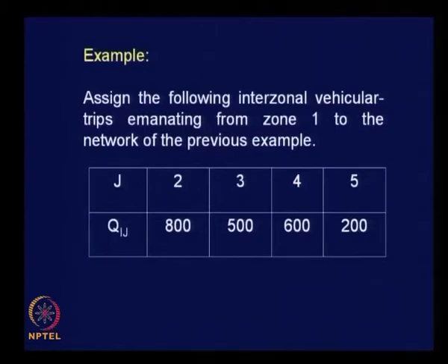To have a realistic idea about traffic volume, it is very important to convert the different types of vehicles into equivalent passenger cars. So these numbers indicate PCU values, otherwise you will not be able to check whether the capacity of a link is reached or not. That can be assessed only based on the traffic measured in terms of PCU.